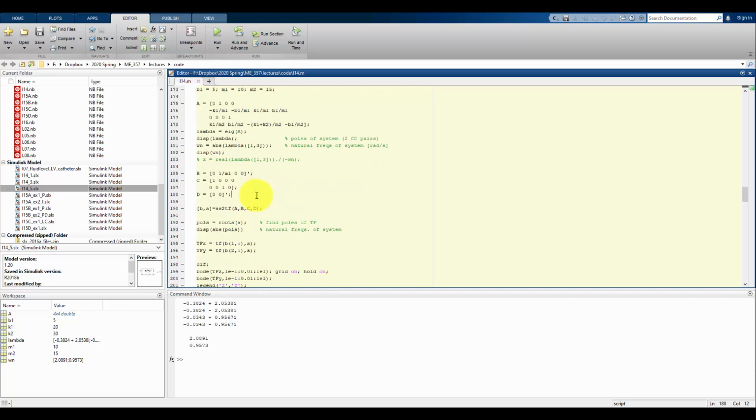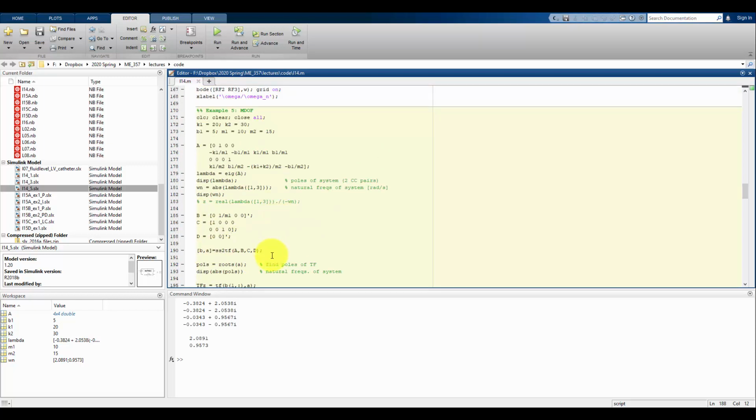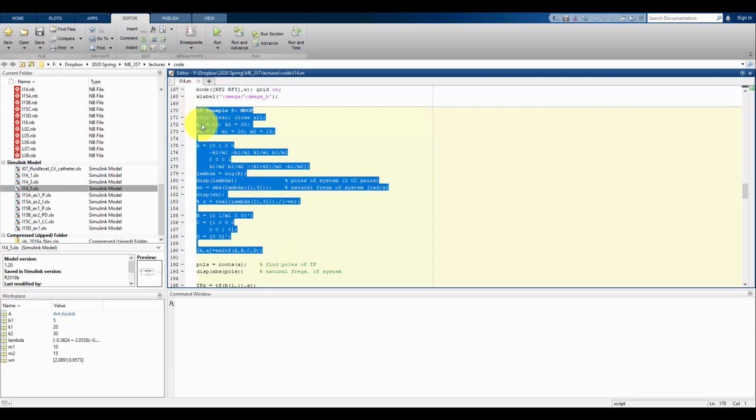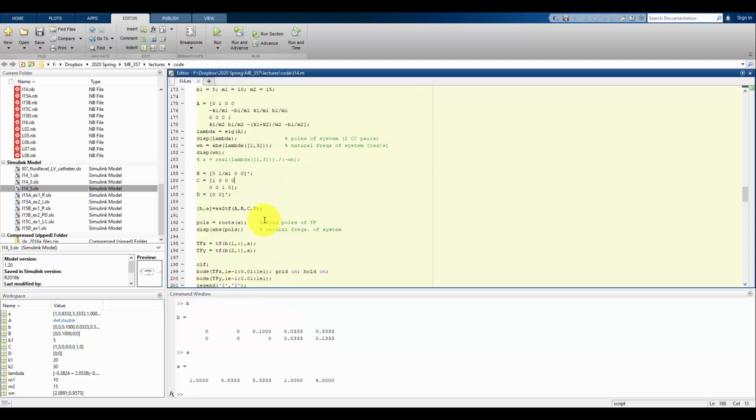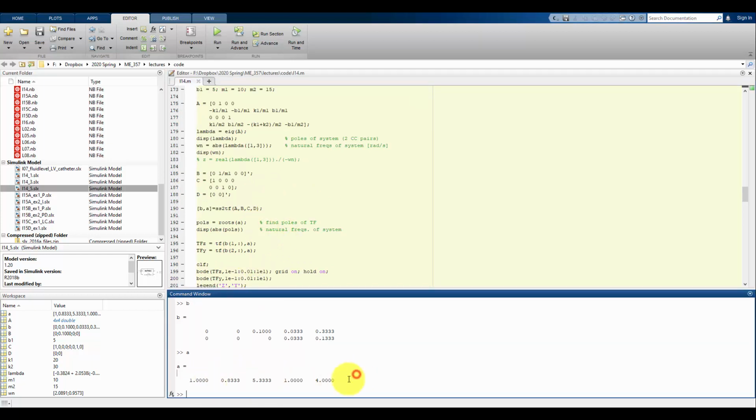Now I can make the other matrices, B, C, and D, again from the slides, and then use the SS2TF function, and we're going to get the exact same results as if we started in Mathematica and then applied all of the numerical values. SS2TF gives us 2 outputs: a B value, which are the 2 numerators of our transfer functions, the first one for Z, the second one for Y, and one denominator that they both share.